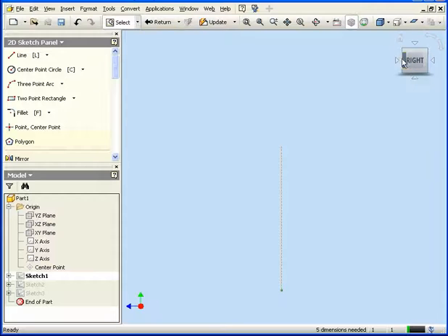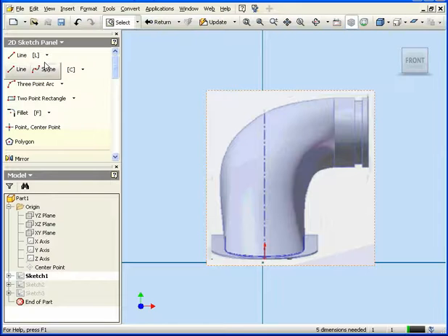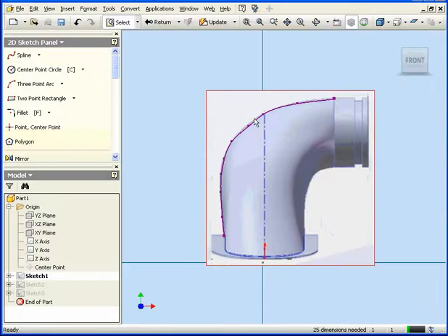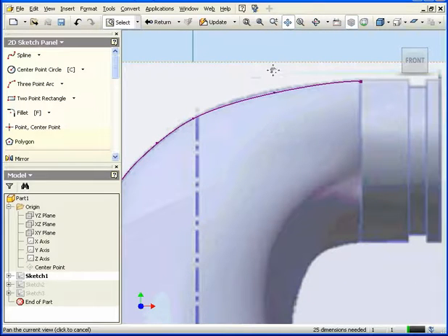Now let's go back to sketch 1. Let's create a spline here that follows the shape of this image. We'll start from this corner. Okay, right-click and create, and right-click done. When we zoom in, you see that we need to make some minor adjustments to our spline in order to line it up better with our sketch. I'm going to do that right now.